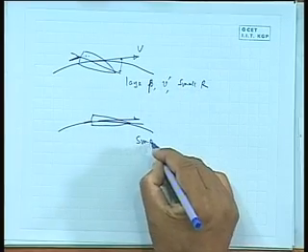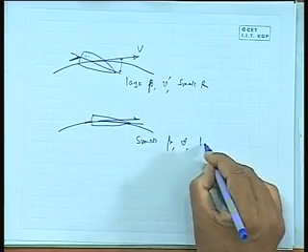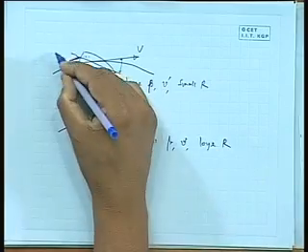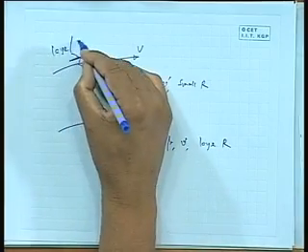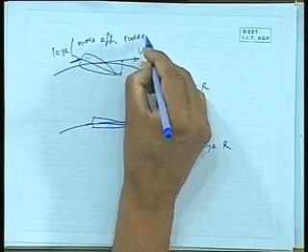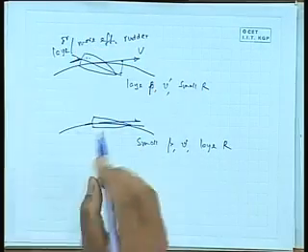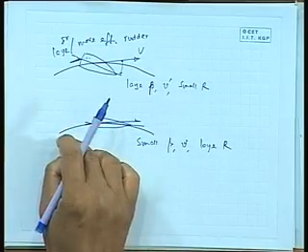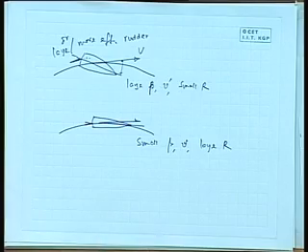This is small beta, V dash, large r. This is large or more effective rudder. Large delta r or more effective rudder, small delta r or less effective rudder. So, if the rudder is very effective, it will turn fast, with smaller radius, but of course larger drift angle, and obviously it will slow down more because there is a large angle you are giving.